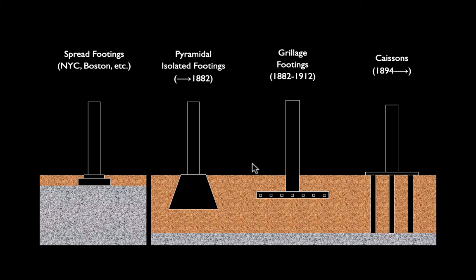These were good in Chicago because for calculation purposes, they didn't like walls. Because the wall could again go over several different types of soil, you never quite knew what was underneath it. They wanted to limit differential settlement. And so they could confirm the soil underneath a single column much more easily. They could do simpler calculations for that. And so they tended to use columns instead of walls, whereas New York and Boston used walls.